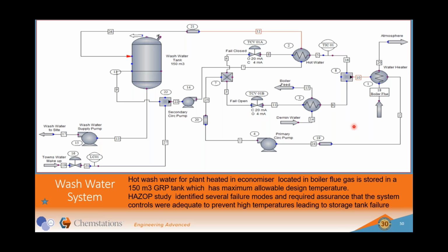Essentially, we used a dynamic simulation to come up with the design, which would enable us to size the valve, enable us to look at the response of the temperatures in the tank, and just general behavior. But it also enabled us to look at challenges. What happens if that valve failed open, for example? How quickly would this tank temperature go up? So this is basically what the challenges were.